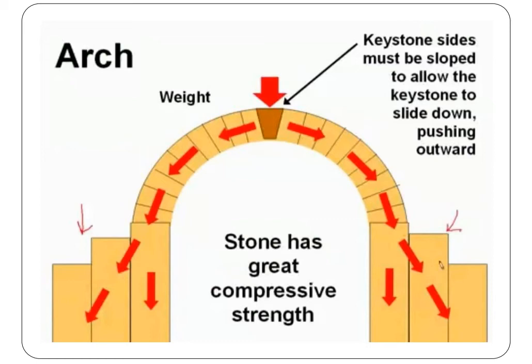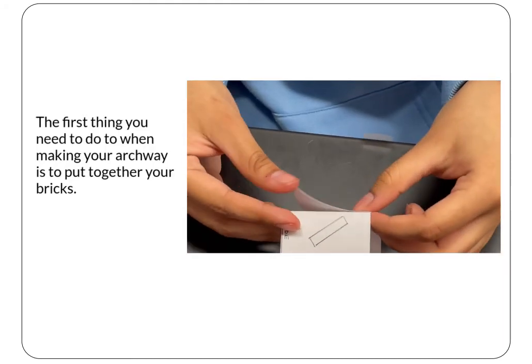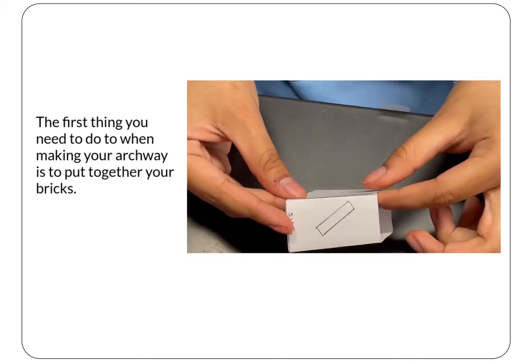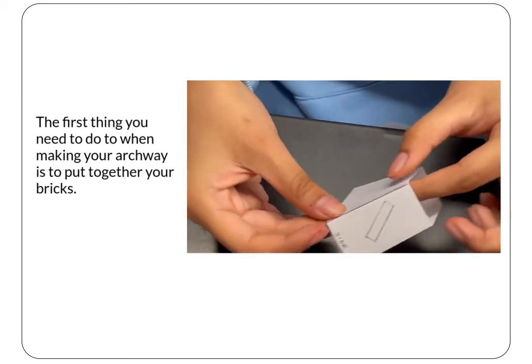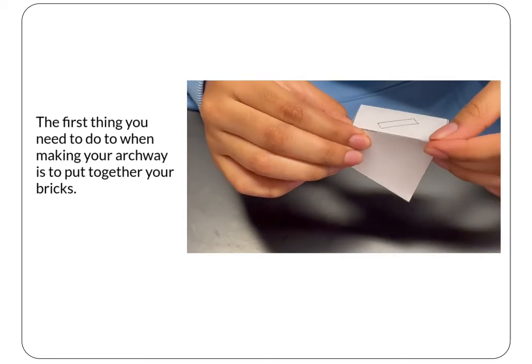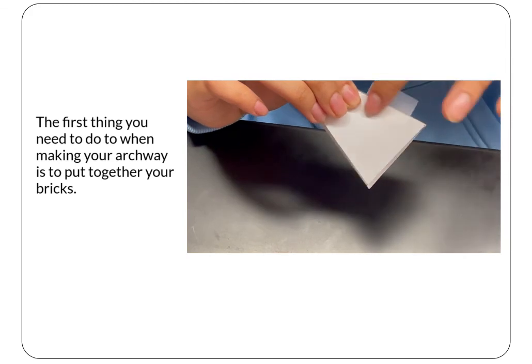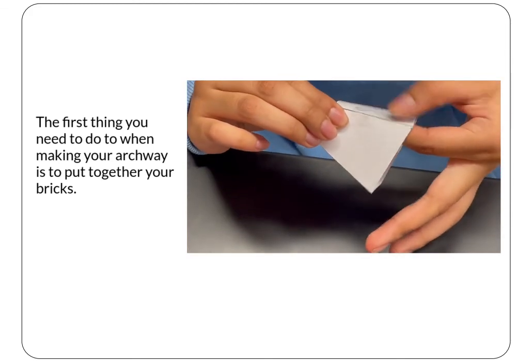This last activity, you will be building some bricks that are specially shaped so that you can build your own gravity-defying archway. Today, we're going to be building our archways with bricks. Cut out each of the 6 brick templates and fold along the solid lines. You want it to be as perfect as possible so that each brick looks identical. This will help keep your archway stable. Once you've made your folds, secure each brick structure carefully with tape.